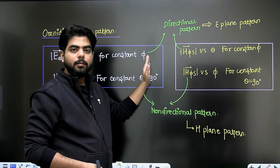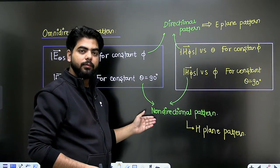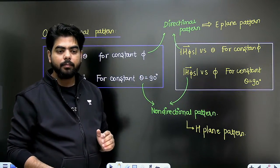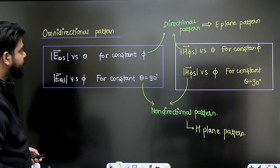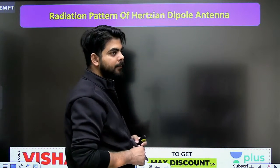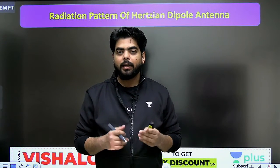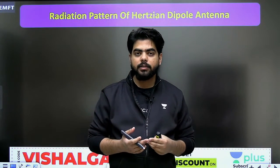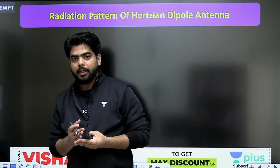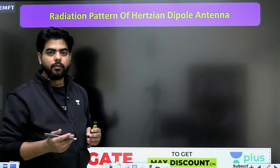If phi equal to constant plane is given, you will call it as E plane pattern, and if theta equal to constant plane is given to you, you will call it as H plane pattern. Clear? चले आगे चलो. So let us try to understand the radiation pattern of Hertzian dipole antenna. How can we understand the radiation pattern of Hertzian dipole antenna? Does it fall under the category of isotropic, directive or omnidirectional? So let us try to have an idea on this.